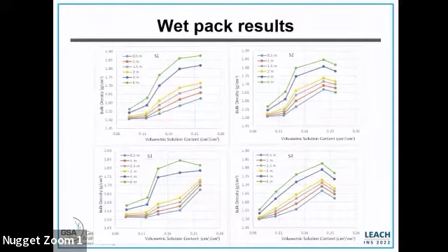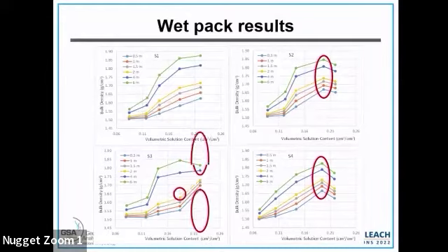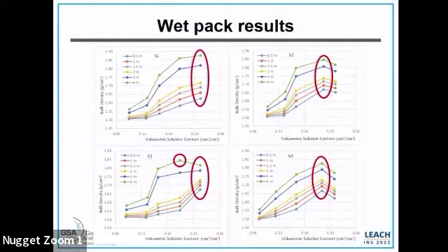As you can see here, this is ore type 3 and 4 and 1 and 2. For ore types 2 and 4, you can see the critical water content was found right around the major collapse of structure at about 22%. And for ore 1 and 3, they were about 19. I'm sorry, the first one is at about 19, this is about 20%. For ores 1 and 3, they are about 22%. So when the major collapse starts occurring, we will do everything we can to avoid any profile reaching that.